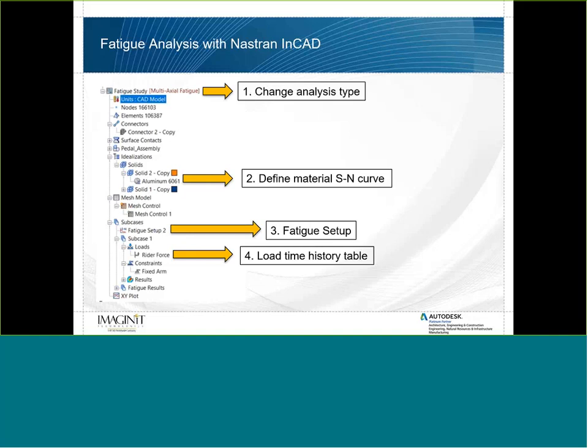The way that we apply our load, whether it's a load or a pressure or a moment, we'll need to apply a load time history table. For each load, we'll need to apply it in a way that matches our stress ratio. Is it going to be applied where it's loaded and then unloaded, or will it be loaded in tension and loaded in compression as well? So we'll need to apply a load time history table that matches the stress ratio that we're going to be using.